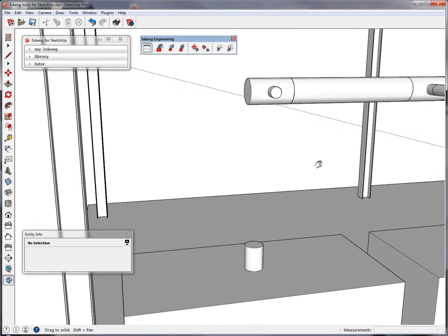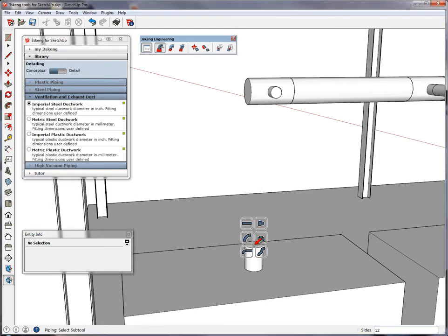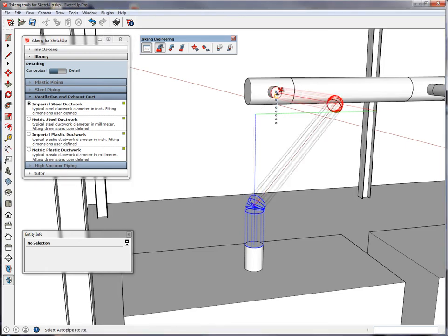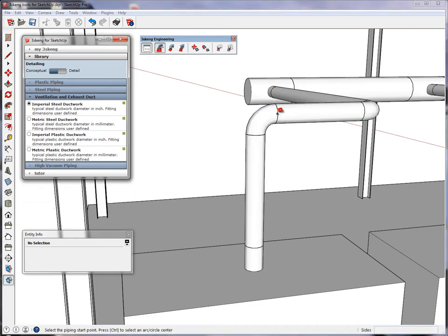But our software engineers went one step further, and we came up with the following: by clicking the start pin and the end pin, it will automatically calculate which possible connections you can make, and if you make a left click, it will give you a variety of possible connections from the starting point to the end point. In this case, we just take our radius to diameter ratio of 1. And by now clicking left one time, the connection is done. I don't think it can be any faster than this.